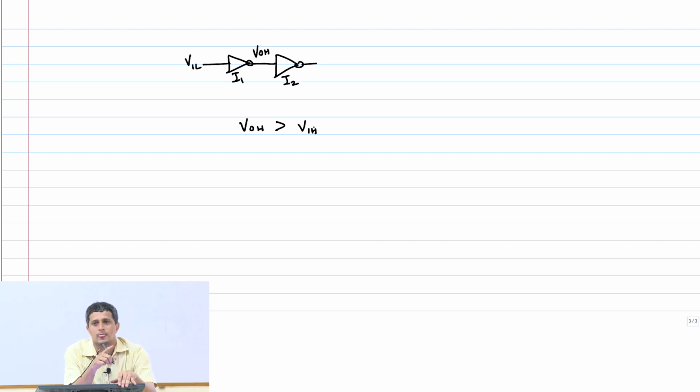Which means that if there is a noise pulse up to this magnitude, the difference of VOH and VIH, it should be fine. My VOH is somewhere here. My VIH is somewhere here, right? This is VOH, this is VIH. VOH is above VIH. As long as that's done, taken care of, it's a logic high, no problem.